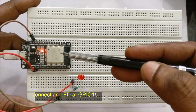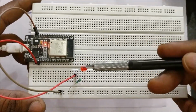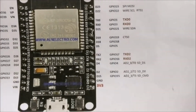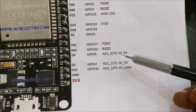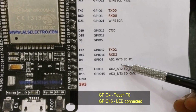Now let us connect an LED at GPIO 15 and then test the sensor. GPIO 15 is the third pin from the right bottom, and the touch sensor T0 is at the fifth pin, GPIO 4.